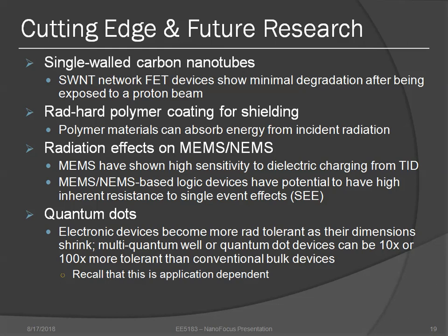There's also some research going on in regards to radiation-induced MEMS and NEMS failures and potential hardening techniques for those. This is not a well understood field at this time and is primarily focused on devices fabricated in poly and single crystal silicon and silicon dioxide with characteristic dimensions of tens to hundreds of micrometers. So, fairly large in terms of where we are today with nanofabrication.